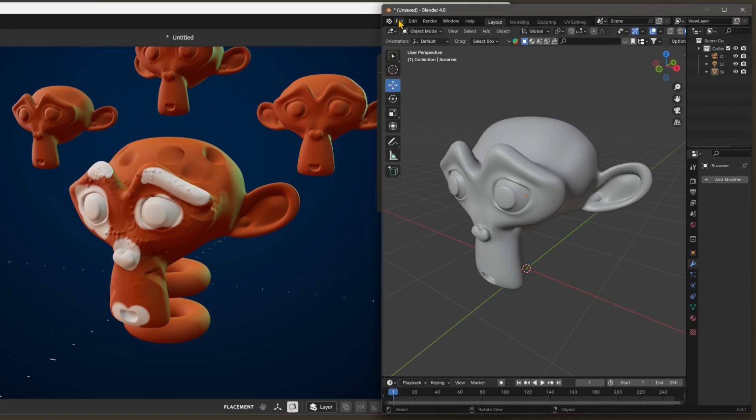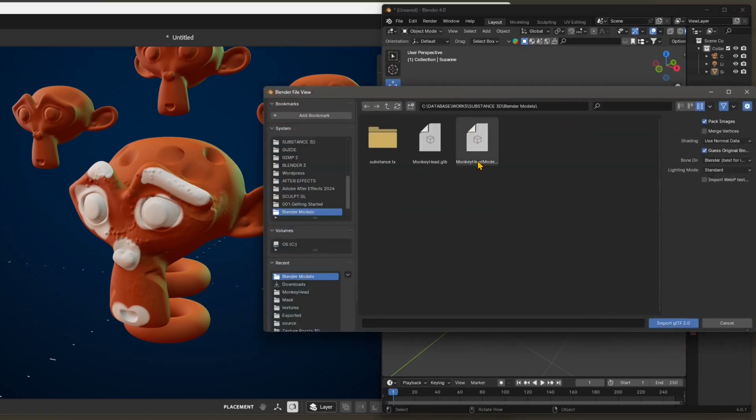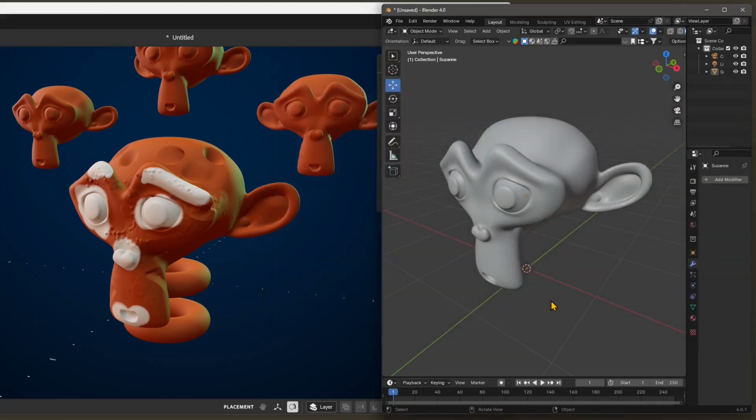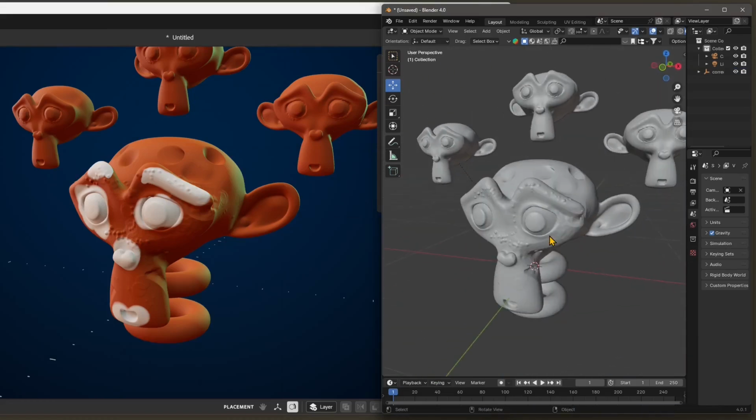And go into Blender. And now I'm going to go to File, Import, and GLTF. Navigate into the folder where I exported the last file and then import. And again, you just need to wait. Now, if you created a big file with a lot of polygons, you need to wait more. So be patient, and eventually it's going to load. And this could take a few minutes depending on how big your scene is. There you go. So I now delete the previous monkey head, and this is the scene that I have created in Modeler with all the sculpting, all the details.